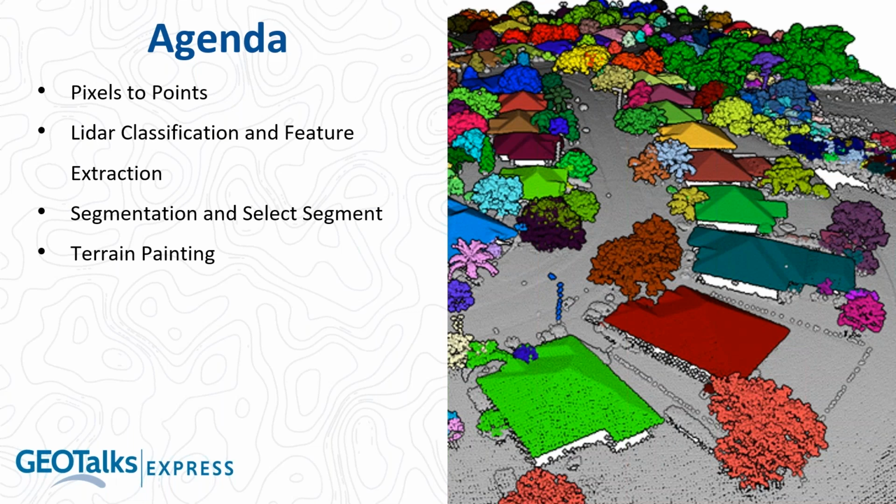We'll be looking at some terrain painting. There's some updates to terrain painting in this new version of Global Mapper. Terrain painting is now part of Global Mapper Pro, and it's a great way to manually edit and manipulate a raster terrain surface. Going along that theme of terrain analysis, there's an automatic break line extraction tool now in Global Mapper Pro, so automatically pulling out vector features for changes in elevation or curvature in the terrain grid.